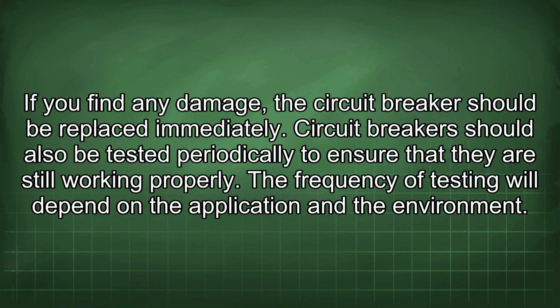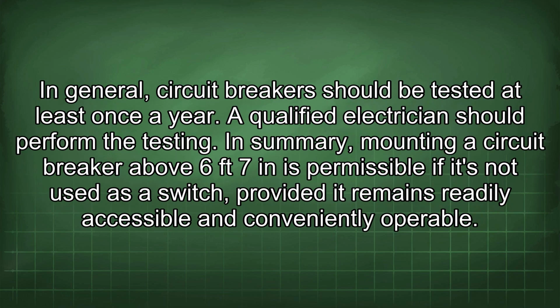Circuit breakers should also be tested periodically to ensure that they are still working properly. The frequency of testing will depend on the application and the environment. In general, circuit breakers should be tested at least once a year. A qualified electrician should perform the testing.